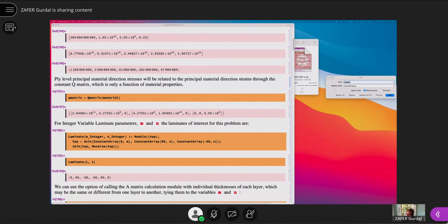So coming back to things that we haven't done and won't have the time to do: interlaminar stresses and constraints associated with design are important when it comes to shear failure. We haven't looked at shear failure between layers and designing for shear failure between layers. But as I said, all the methodologies that we do and the failure constraints we implement are applicable to those as well. It's just a matter of doing a different analysis. Of course, if you are doing sequential linearization, then based on the new theory, there will be a new equation for derivatives. That is something that's going to make it more complicated. So that's one of the things that we have not done.